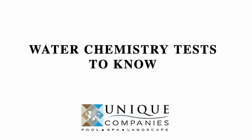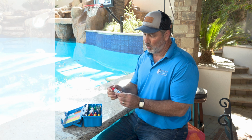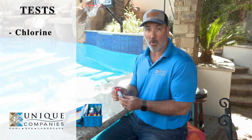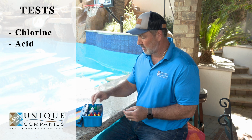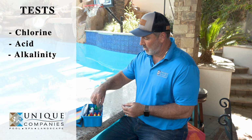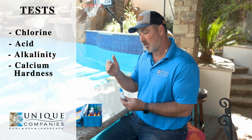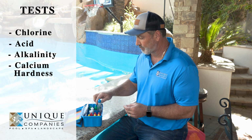So if you have test strips, they work okay, but they're not as accurate as some of these drop tests. With water chemistry, there's about 5 different tests that you need to do to really get your water dialed in. Obviously most of the pool service companies do the chlorine and the acid. We'll show you how to do that next with some of the droplets. Alkalinity, which buffers pH. Calcium hardness, which is how much calcium you have dissolved in the water of your pool.